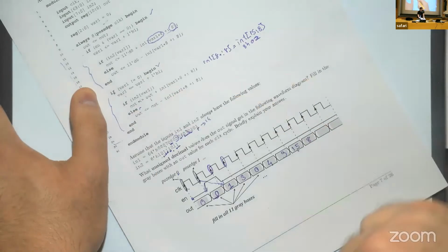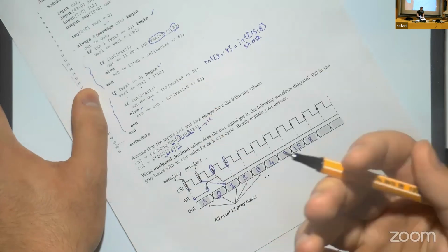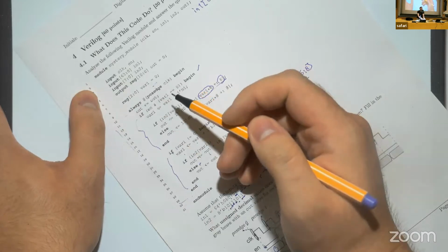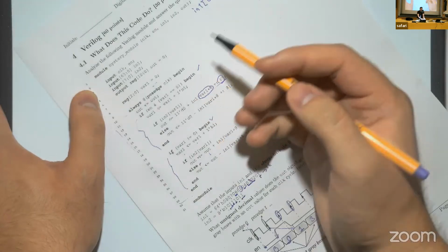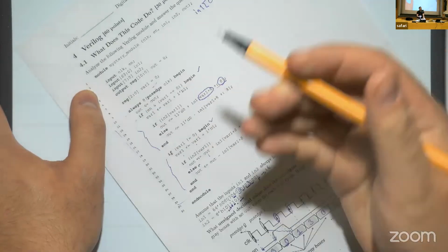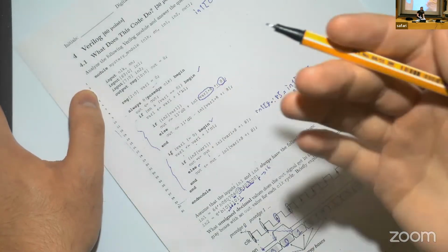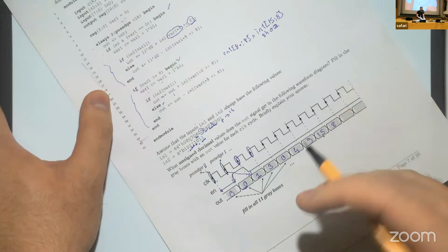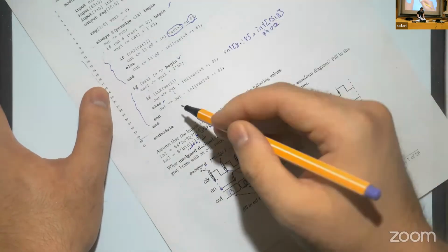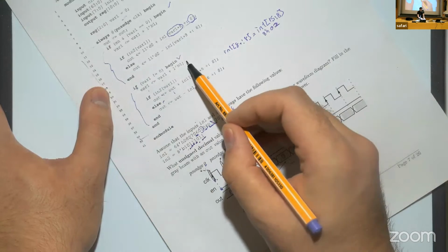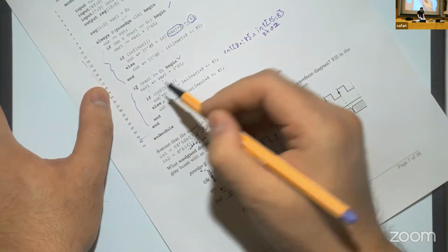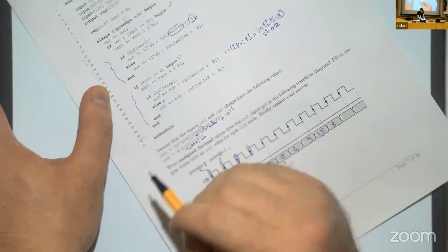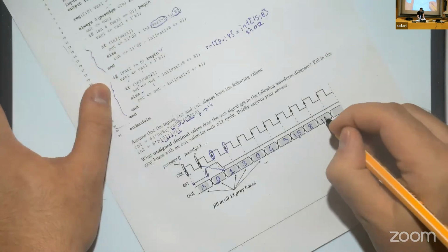So we increment var 1 by 1, which makes it 8. But the problem here is var 1 is 3 bits. So 8 is actually 4 bits, right? 1, 0, 0, 0. What happens is that var 1 takes the least significant 3 bits, which means that you reset var 1 to 0. So in the next cycle, var 1 becomes 0 again. But let's execute this cycle. Var 1 becomes 0 here, we check the 7th bit of in2, which is 1. And then we perform addition, 8 plus 8, which is 16.